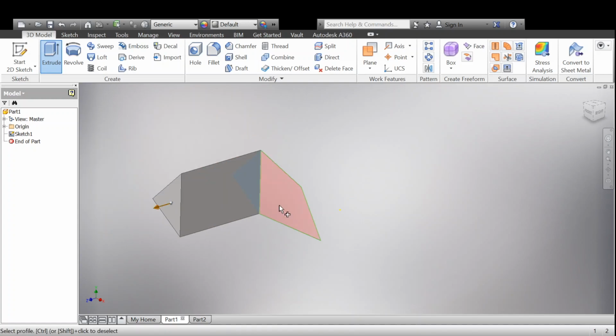Now if I click here, I could extrude them both at the same time, and now it looks like one giant solid. But again, I could choose this X here, go back to extrude, and I could possibly just extrude one of them. But again, the sketch doesn't disappear. So give me a second so I can show you again. I click here. This part's going to extrude.